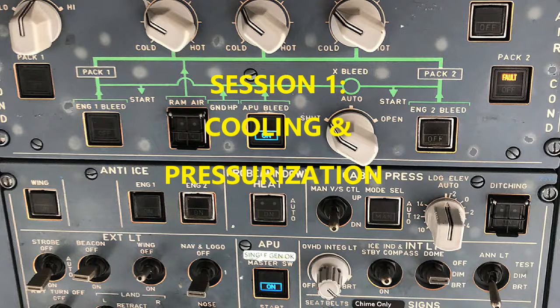We're interested in the pack flow control valve position, and then we also have the pack bypass valve position that's going to be indicated. And this particular display is an arc indicator. It's not a vertical line situation. It's actually an arc, and the arc is always green. It's going to show the position of the turbine bypass valve that's in the pack. That position is going to range from fully closed to fully open. Fully closed is C, fully open is H for the designation. Okay, so those are your positions.